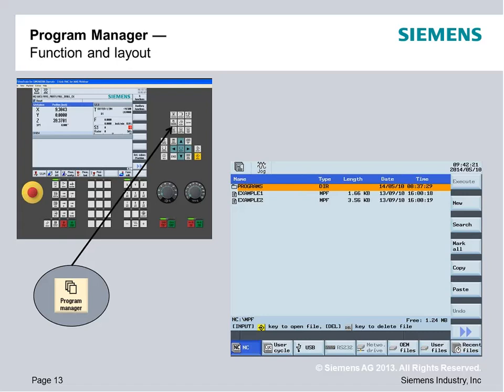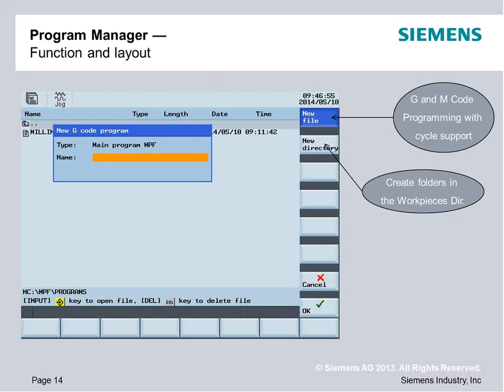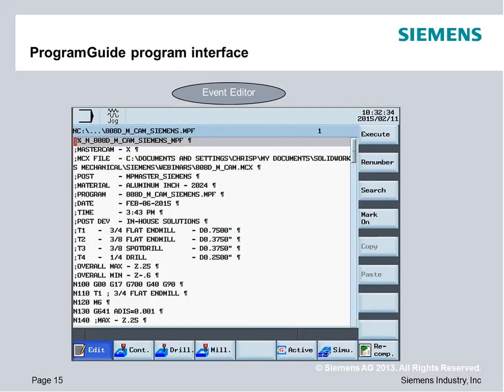From there, we're going to switch over to our program manager section. This goes into the area where we actually manage part programs. So we're going to start transferring files in and out of the control. We're going to build some directory structure, create some file structure so we can copy programs in and out. I'll show you some tricks as to how to streamline how you methodize your parts and track your parts.